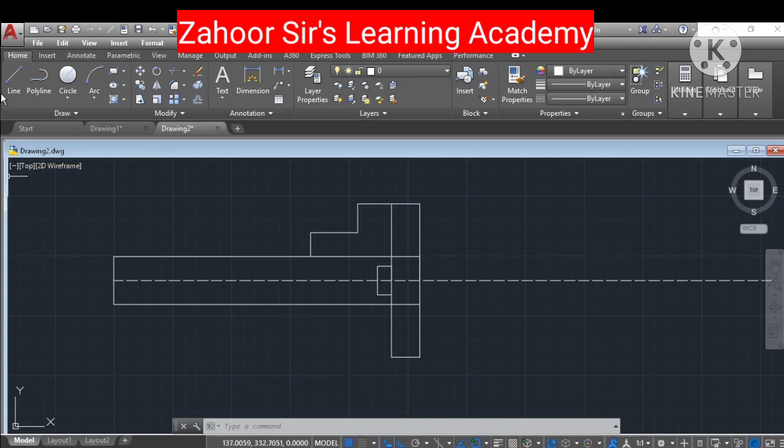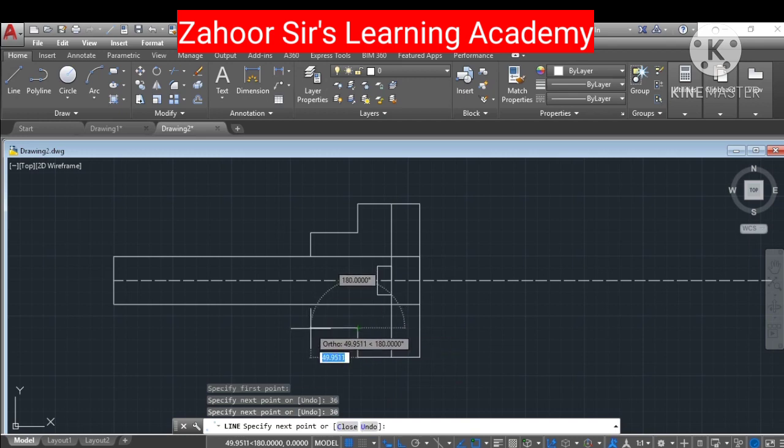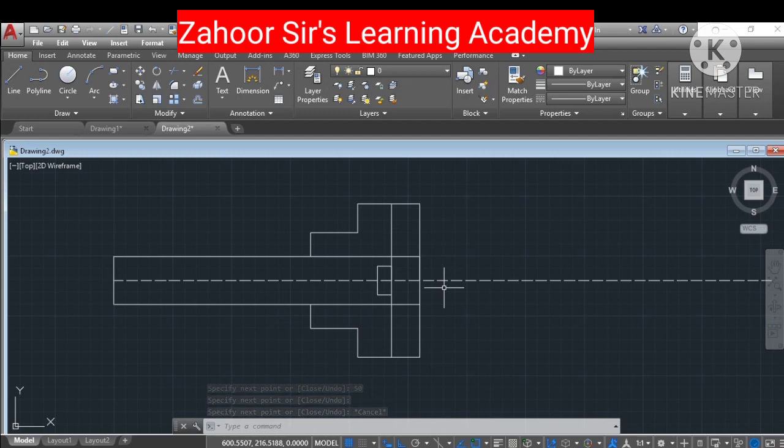So the same I can do it again. I'll pick the line command, and from this point I'll go this end 36 mm, then press enter, then down 30 mm, then enter, then to this end 50 mm, then enter, and then 25 mm down and drop it there. So this is how we have drawn one side of the diagram.